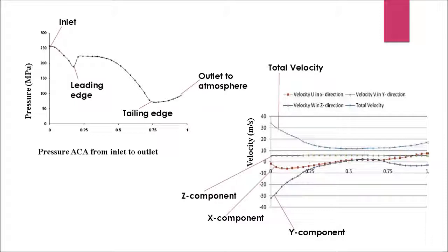The velocity component u in x direction, starting from small value near to 0, increases gradually along the streamline in radial direction of the blade. The velocity component v in y direction starts from a large negative value and increases gradually along the streamline and stops at the value a little less than 0.